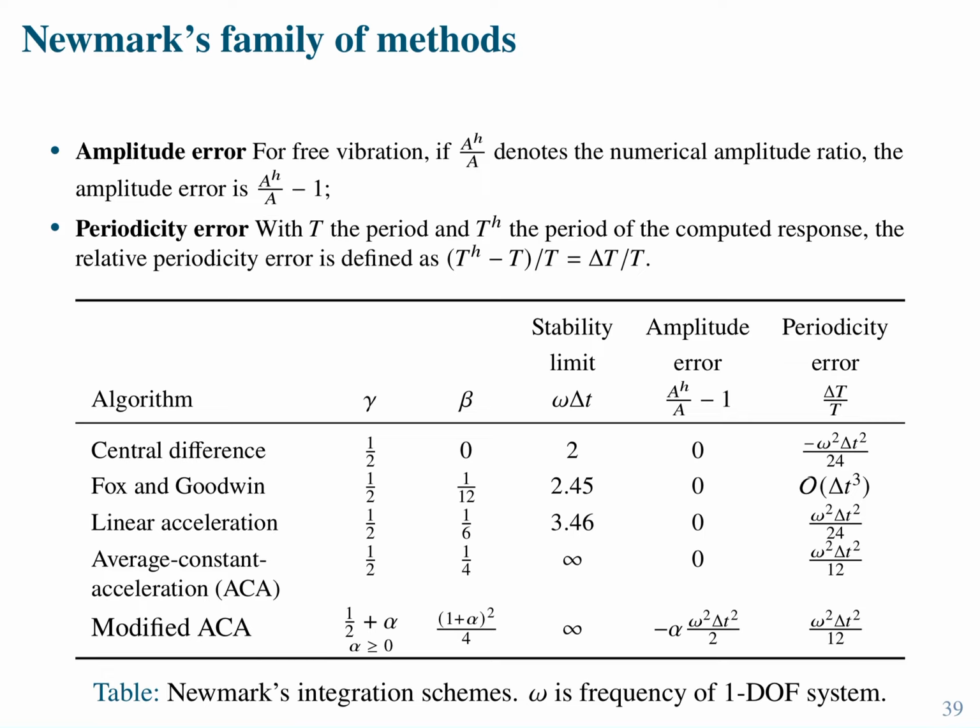And we tried Bathe's method. I will talk a little bit about that approach. And that also didn't solve the problem. So actually we have an open question we cannot resolve because we don't have a proper time integration scheme to deal with fracture propagation using enriched finite element methods, which is very, very annoying. And it's been in the back of my head for 5 years. But to answer your question, you pick a method that works until it doesn't, and then you move to try something else. In terms of implementation, yeah, it is the same effort. I would argue that for all implicit methods, it's the same implementation. If you have an explicit approach, you choose it for a simpler implementation, right?